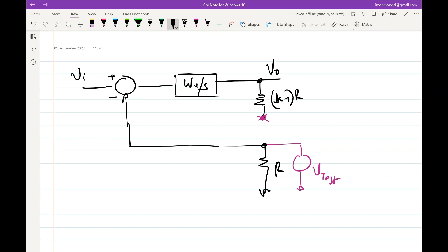Yeah, so the return voltage is minus V test omega u by S, right? So which means that the return ratio, or even L of S in this case, is omega u over S. So this is supposed to be omega u over Ks, right? We have been doing omega u over Ks for the last couple of weeks. So why do you think this is different?